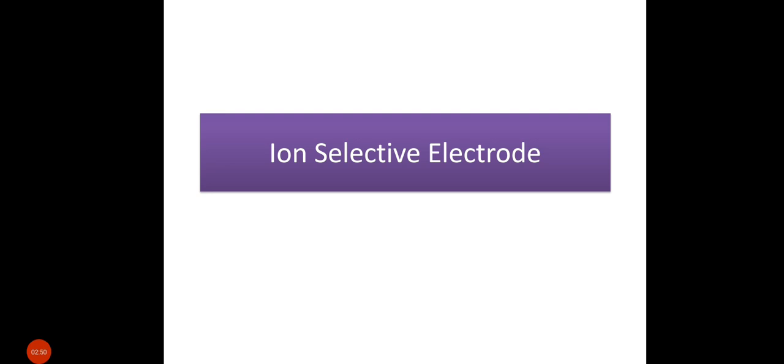These electrodes are classified as membrane electrodes containing an ion permeable membrane that separates the sample from the internals of the electrode. The main advantage of using ion selective electrodes is that they are insensitive to color, viscosity or suspended solids. They are also tolerant to small changes in pH. Response time and reversibility are critical for the performance of this sensor.